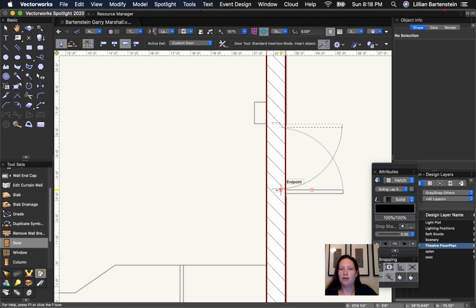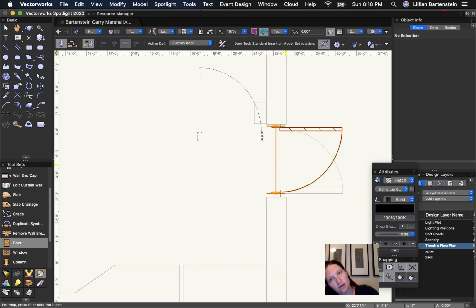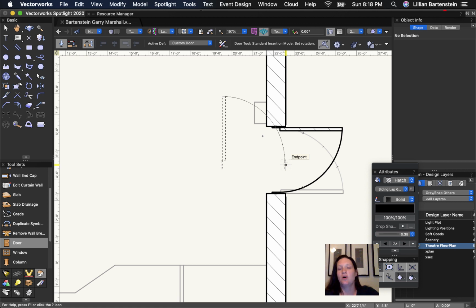This is a little happier. Okay. So if I'm going to use this door as a guide, I'm lining it up so it matches with the door, and I'm hovering over this wall, which has turned a little bit red, and then I click it and it should go into the wall. It's thinking. It's stressing because I'm making a video. Okay, there it is. It's inside the wall.